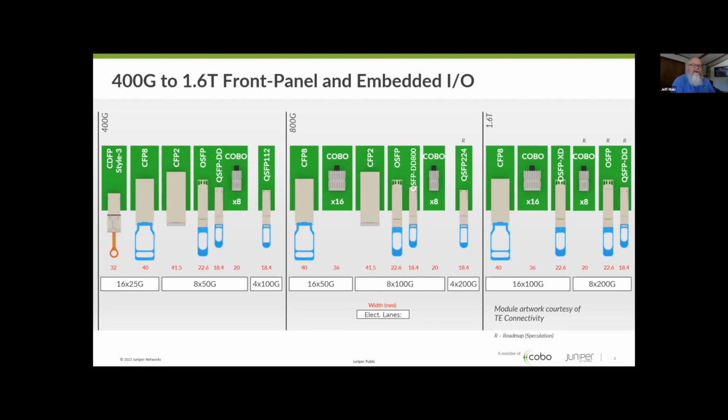the industry. Now, when we go to the 800 gig generation, we see that being updated now with a lot of focus on OSFP and QSFP-DD800. So this has been the form factor evolution so far. Of course, there's still other contenders. Even now, the 16-lane CFP8 module is still in consideration. And I've heard now even some people are taking CFP8 to 1.6 terabit.